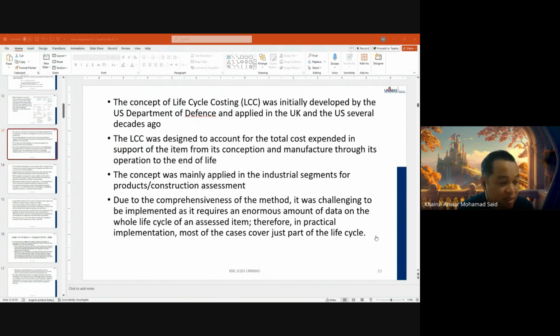So let's reinforce why this is the correct answer. Remember, life cycle costing is a retrospective cost assessment method. It operates like an audit. It requires a huge amount of life cycle data to sum up capital and operating expenditure over time. It doesn't actively change your process design. However, water pinch analysis, the WPA, is the in-process targeting and design tool.